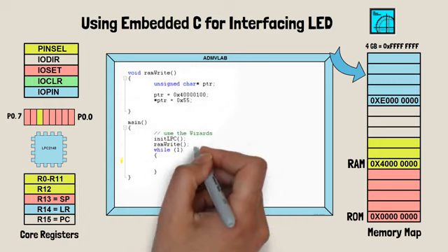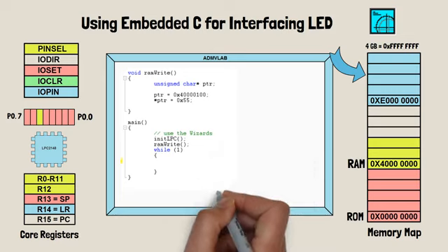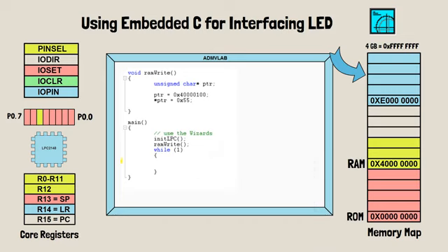Let us now write a simple embedded C program which can read and write any location on the memory map. As usual, in every embedded C project, function main is the entry point. Let us create a new function, called RAM_write. This function is called from our main routine. The simple RAM_write function, using pointer, can now read and write to any RAM address.